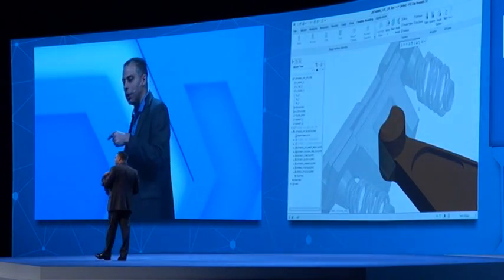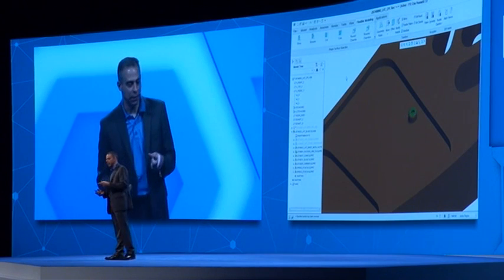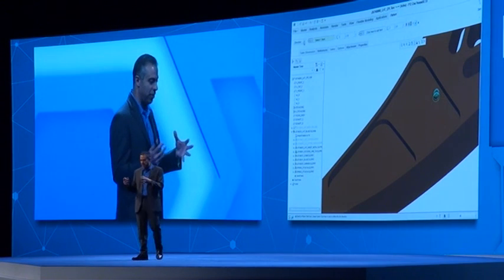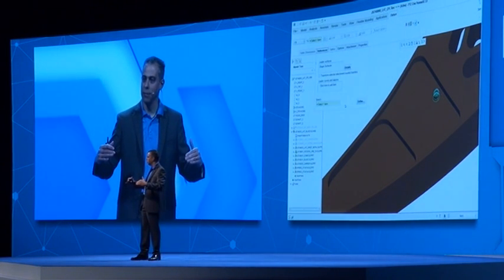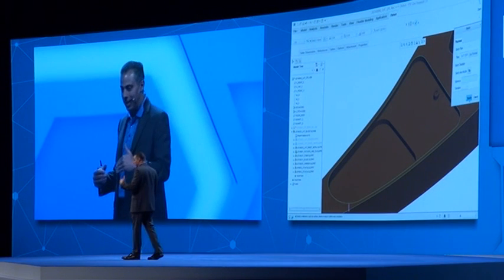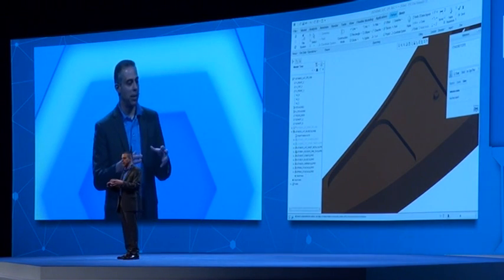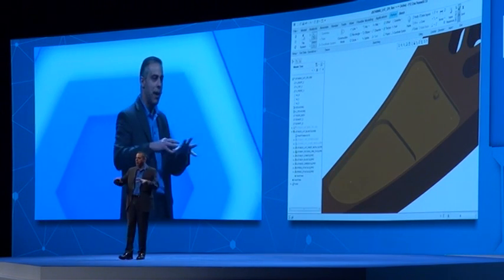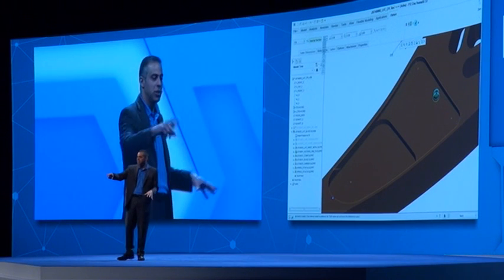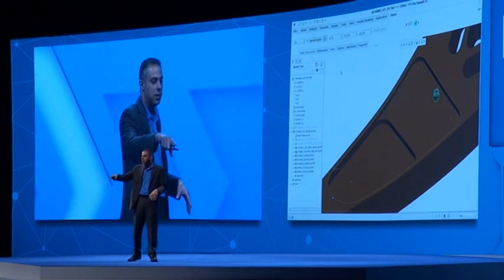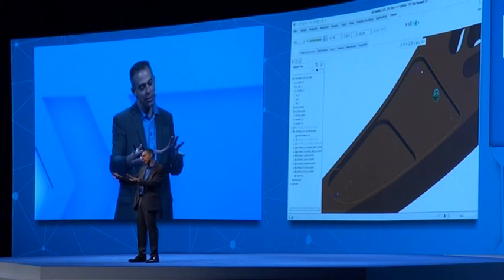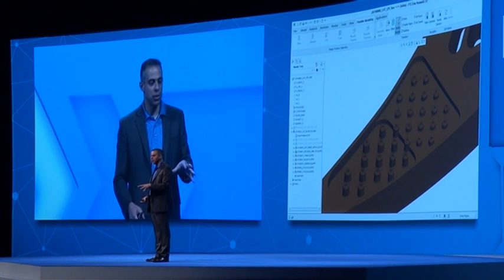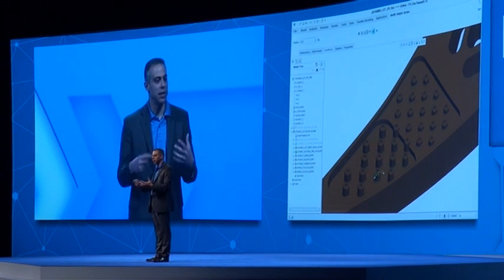We've also introduced a completely new pattern option in flex modeling. It's called a flex pattern. It's a geometry-based pattern, but the strength of this pattern is that it's got flexible modeling technology underneath it. This flexible modeling technology gives the pattern members the capability of adjusting to different topologies as the pattern members go across the surface of the part. So what you see here is we do this fill pattern of this boss. What you'll see is the boss, as it goes across that lip, the rounds, the geometry will all extend down and regenerate just fine. This is a new flexible technology-based pattern.